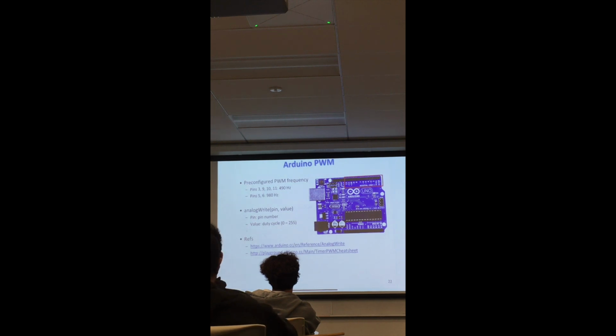But you can program your own. If you want to use some other frequency, then you have to reprogram it. Remember that the development idea is quite basic, but internally it is using a GCC compiler. Which means you can program with the Arduino IDE, and you can also conduct register programming. So you can program it as a regular microcontroller without using Arduino libraries.